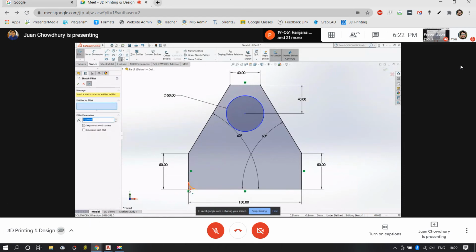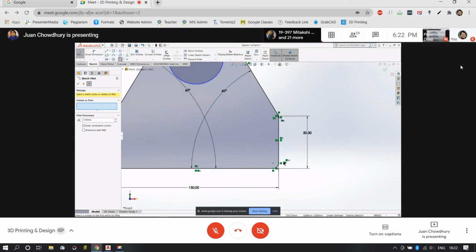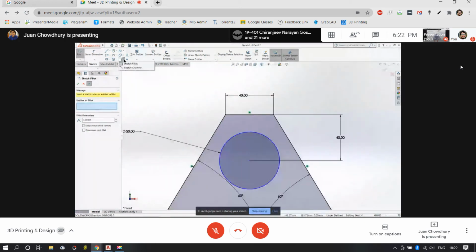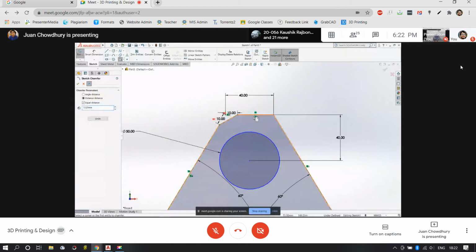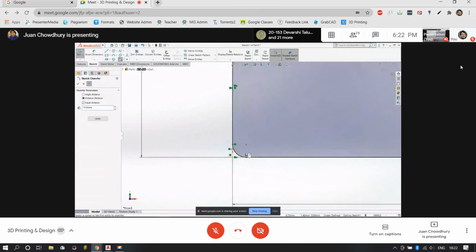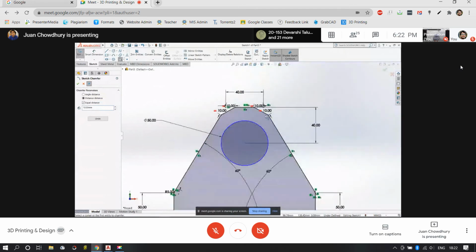Sketch fillet. So what I need to do is just simply click on the corner. As you can see, it has already set by default how the shape will look like, and maybe I can change it to even less, 5 mm. If I click on it, there are some nice beautiful round edges. And then the chamfer one. I'll switch to chamfer. Click on this edge, click on this edge. So can you see the straight lines? And then what you have are some corners. So that's the difference between fillet and chamfer.